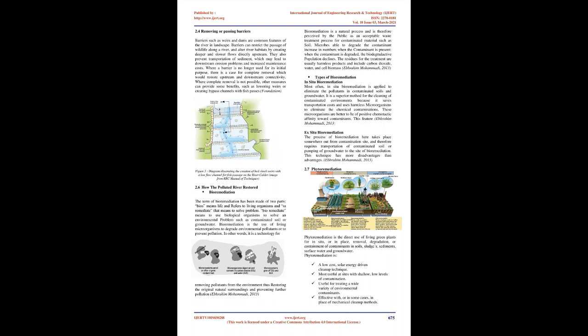There are many novel in-stream enhancement techniques to consider, but most involve introducing some form of roughness in the channel, such as woody material, reworking gravels, or creating berms to create flow diversity, new habitats and areas of refuge. This form of restoration can provide a great opportunity to get local communities involved, as it usually requires a hands-on approach.